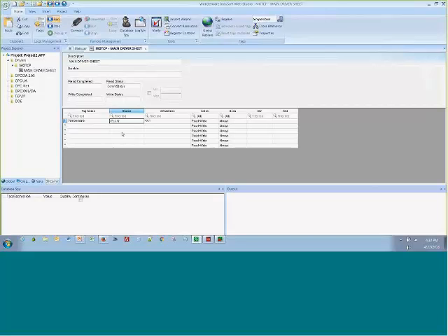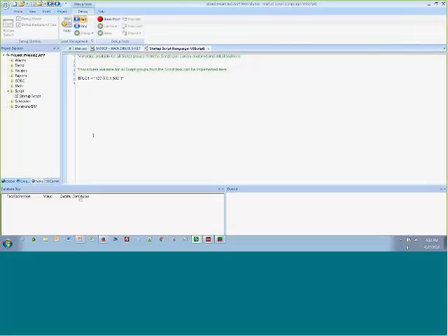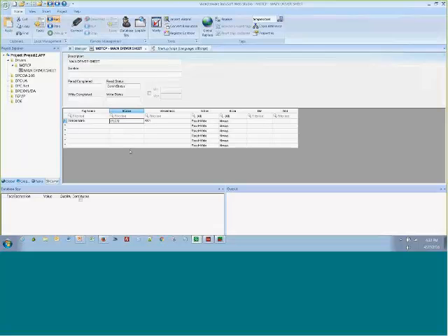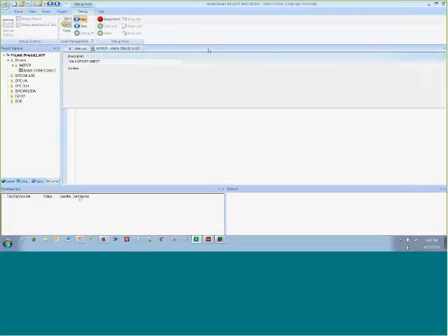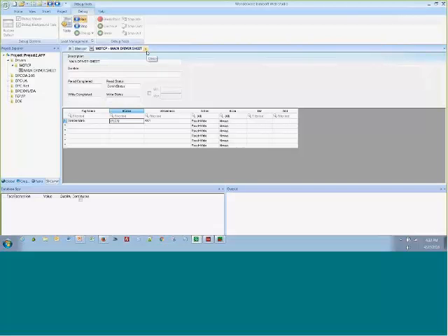I did a project a few months ago that had 23 different PLCs, and of course the IT department decided they wanted to change all the IP addresses, and so all we had to do was come into the startup script and change the 23 PLCs here rather than thousands of them throughout their different line items in the main driver sheet. So it made it very, very nice and easy there. So hopefully that was a good tip and something that will become useful for you as well.